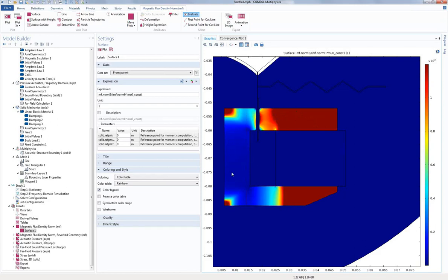Conversely, we might want to add some material in here in the pole piece because there the local relative permeability is fairly small right now. We have approached or almost reached saturation. That's a very, very relevant and interesting thing to look at.